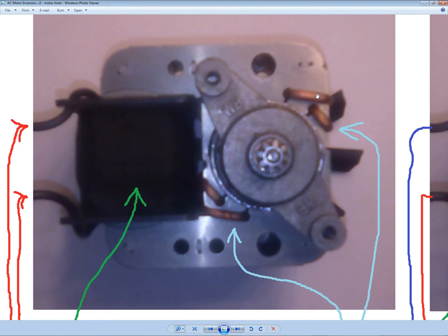But the starter coils are a Tesla invention, and they are induced because the bobbin here of thin voltage coil sets up a magnetic flow in the toroidal stack of laminates, and then that sets up a current flow in these very stout wires. And the current flow throws things off because we only have one over here and one over here, and they're wound a certain way, and they're soldered to themselves to make a closed loop, an electrical closed loop. And that offsets the wiggling such that the wiggling actually will rotate, always in the same direction.